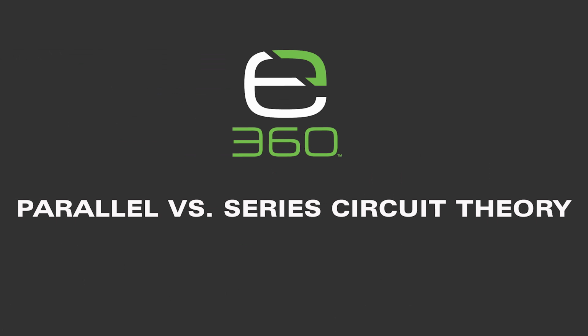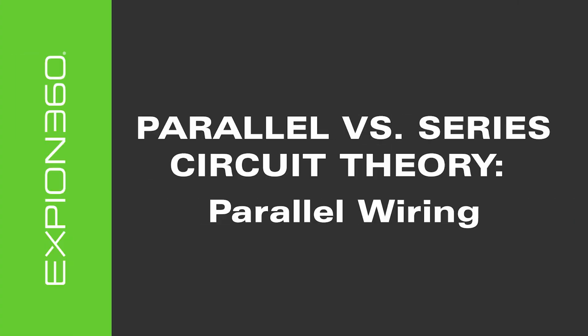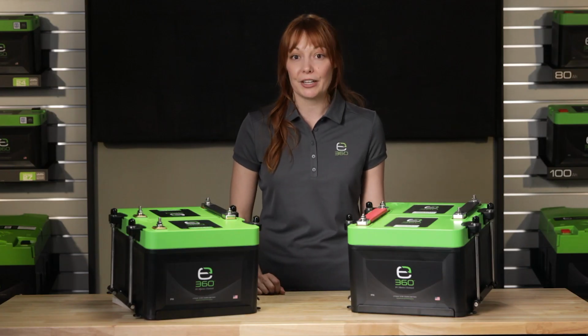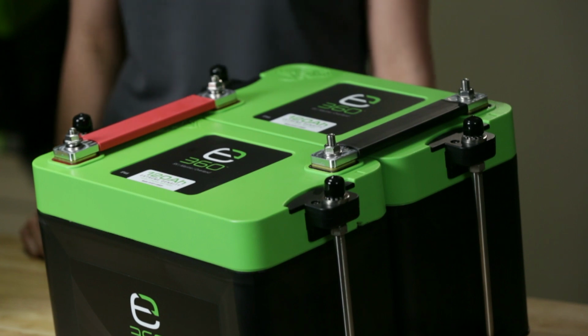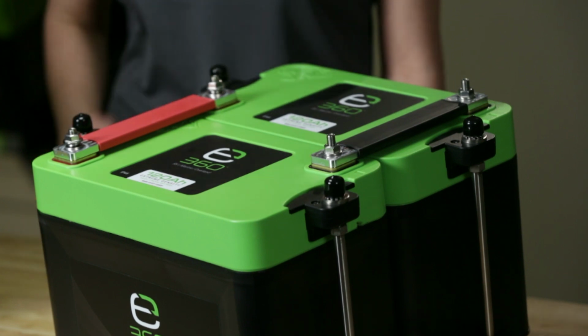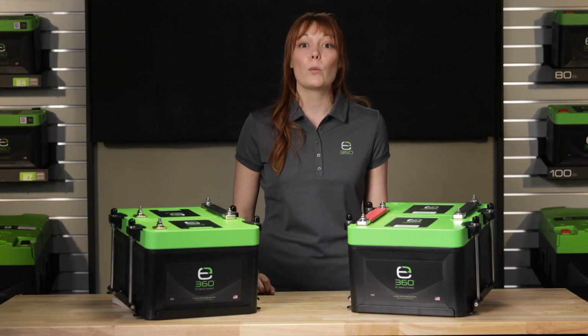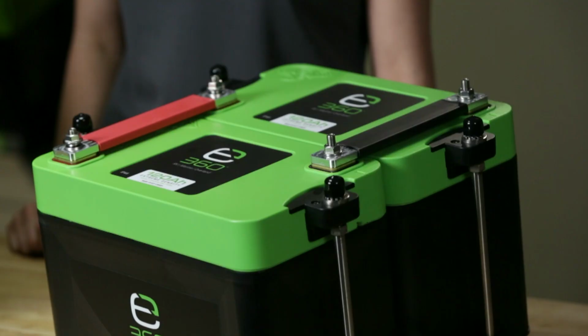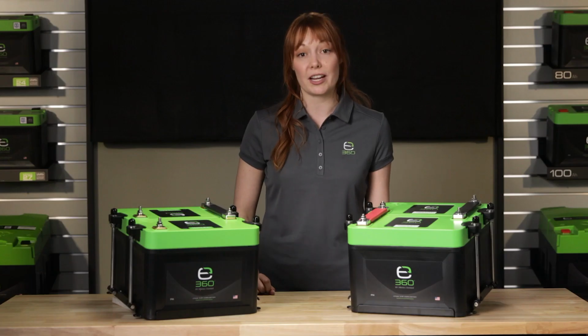In this video, we discuss parallel versus series circuit theory. Let's begin with a parallel wiring example. You can see here how batteries are wired in a parallel wiring configuration. The individual battery terminals are connected positive to positive and negative to negative in strings of up to 4 batteries. When wired in parallel, the voltage remains constant, but the capacity increases. In this example, two 120 amp-hour batteries total 240 amp-hours at 12 volts direct current.